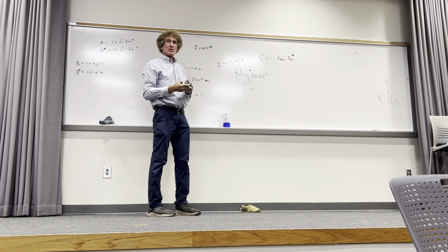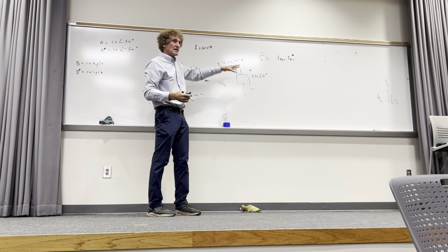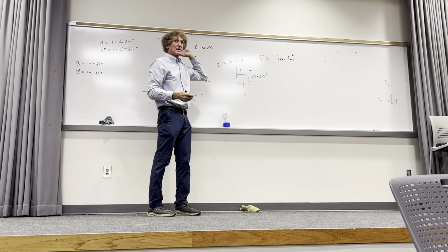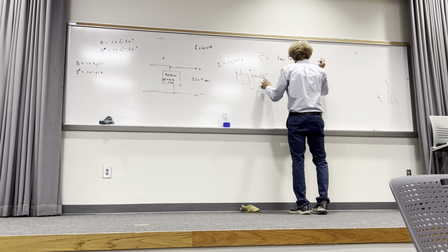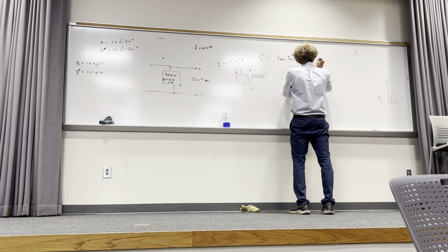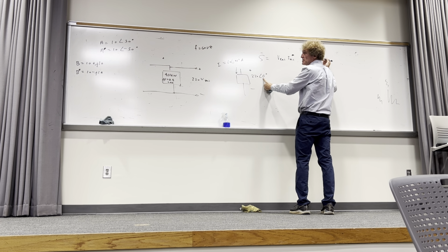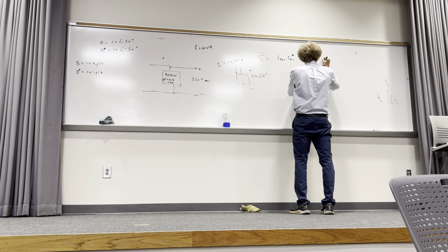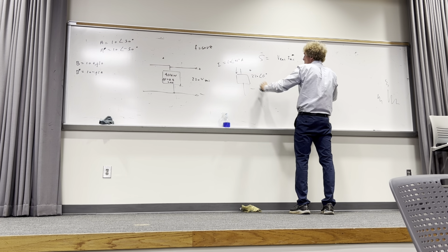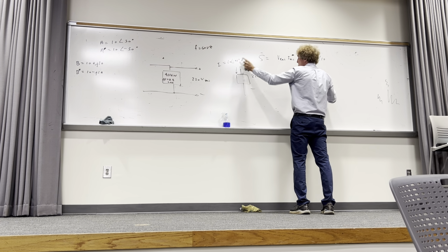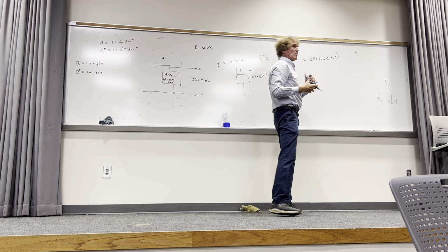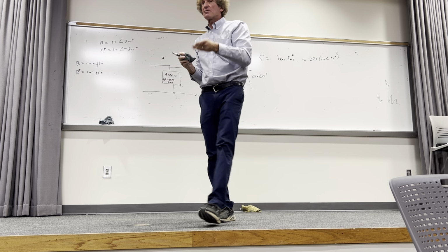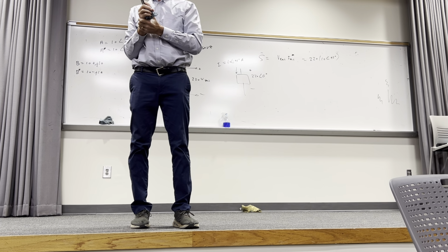The complex power associated with this element, and I've eliminated everything but the circuit element I care about, would be VRMS, which is just 220, at an angle of 0 degrees, so you don't even need to worry about the angle. Times IRMS, 10, but it's conjugated, which means the sign on that angle changes. So it'd be at an angle of plus 45 degrees. Everybody follow me on that? I'm just giving you a concrete example so you understand conjugation, what we're doing.